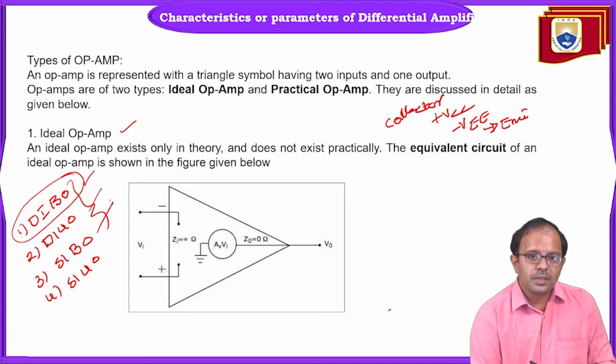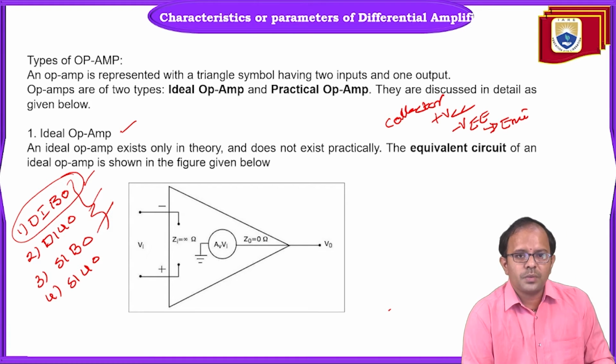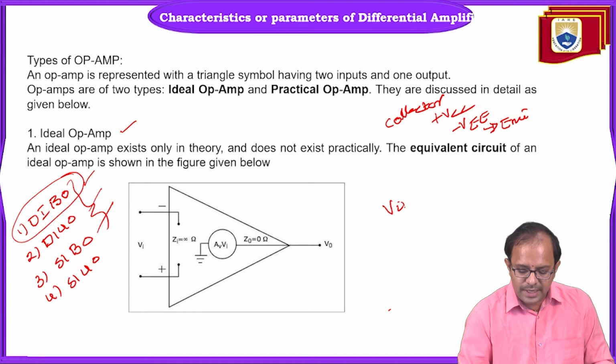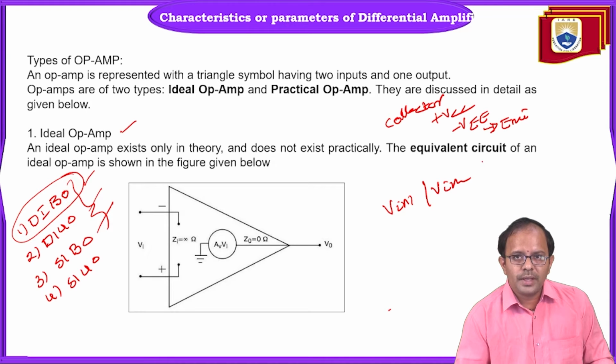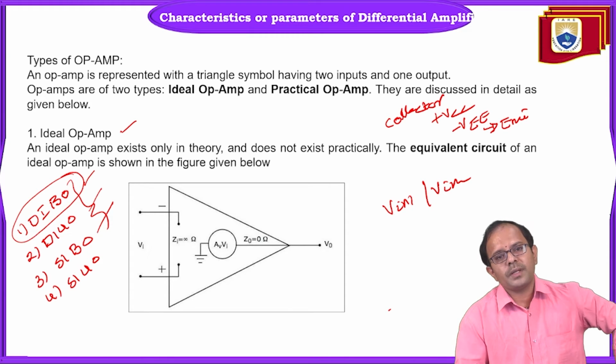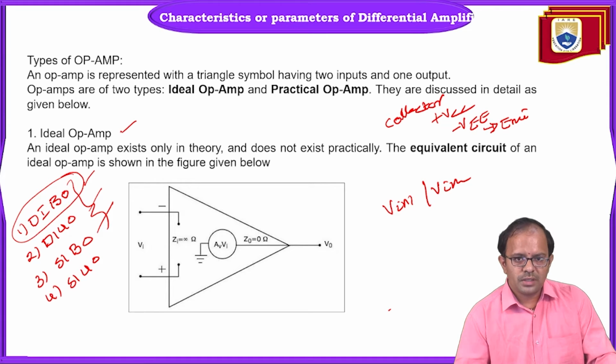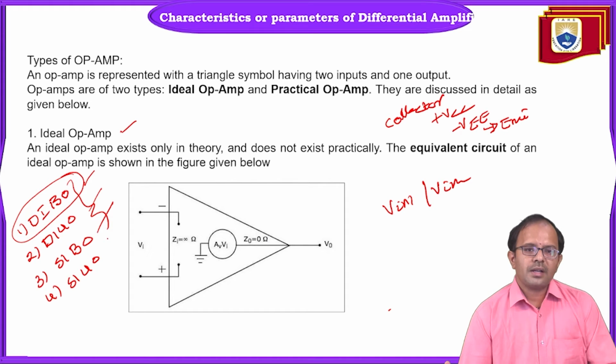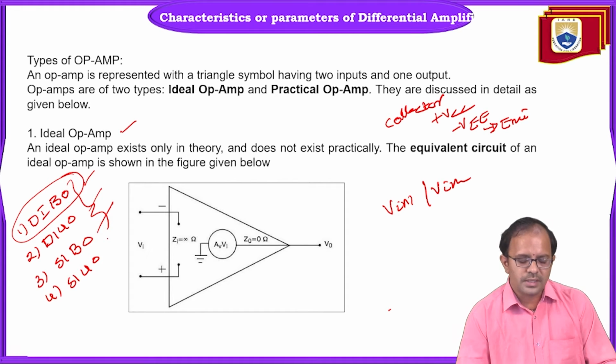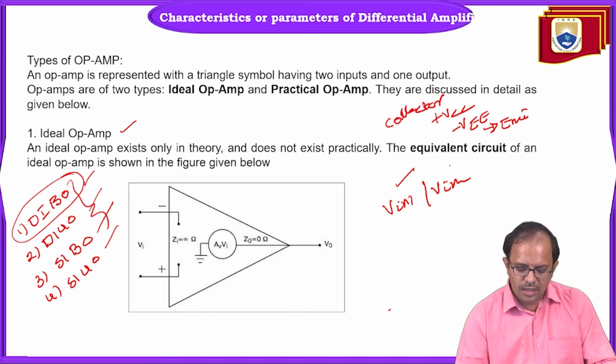In the case of dual input, as we said, we have both Vin1 and Vin2 considered. And in single input, there will be either Vin1 or Vin2. It is not required to apply both Vin1 and Vin2 for the given differential amplifier circuit. Right, that is what single input means. And balanced output is always obtained across the two collector terminals of the transistors. And similarly, single input unbalanced output we have seen. Again, there will be only one input, either Vin1 or Vin2.